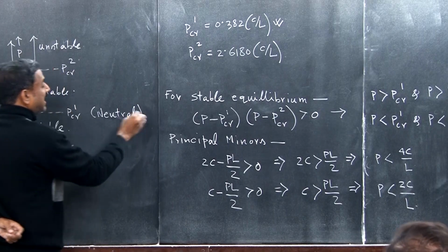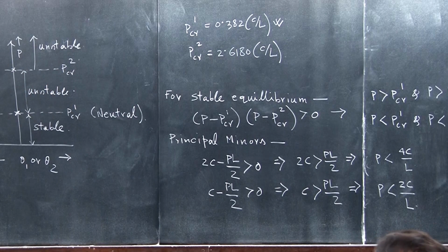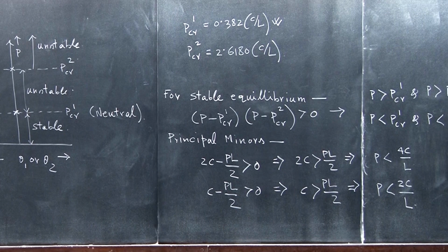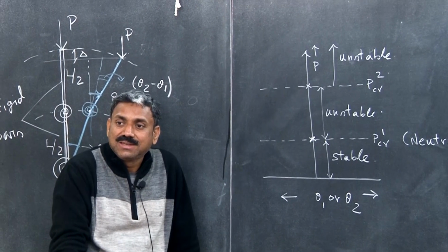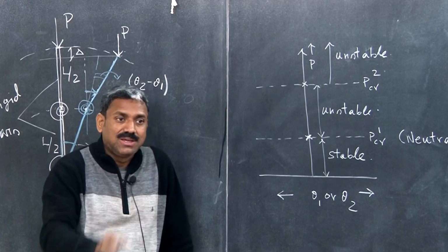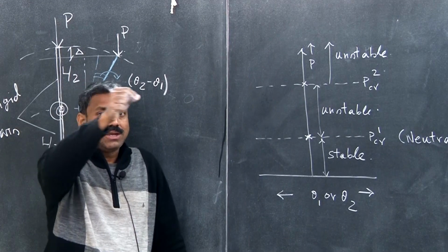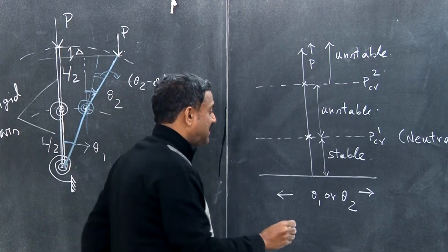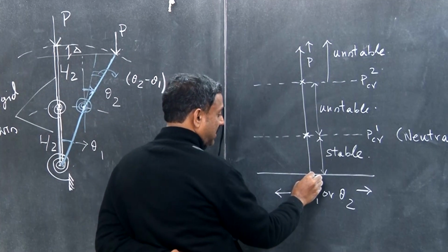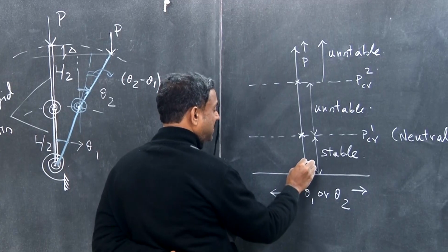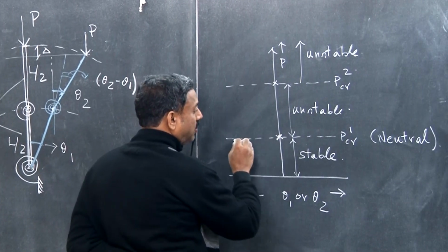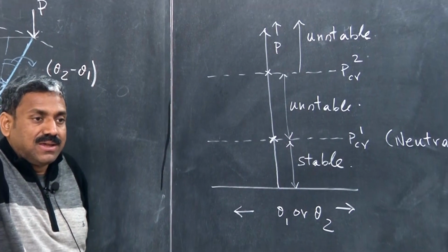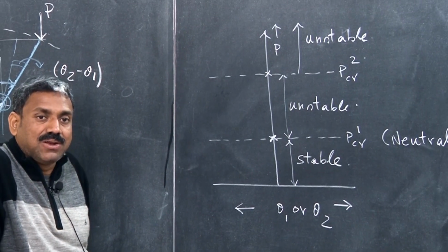And you also recall that when it buckles, just on the verge of buckling, what kind of equilibrium is it? Neutral, because you can perturb it and keep it at any configuration you want, right? That is what we can see. So, what we can see is that the system will remain stable, but then it will bifurcate into a state at the first critical load.